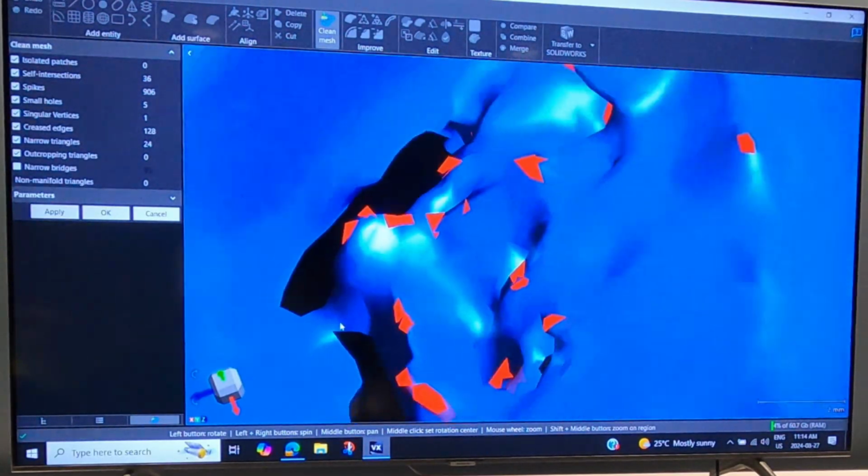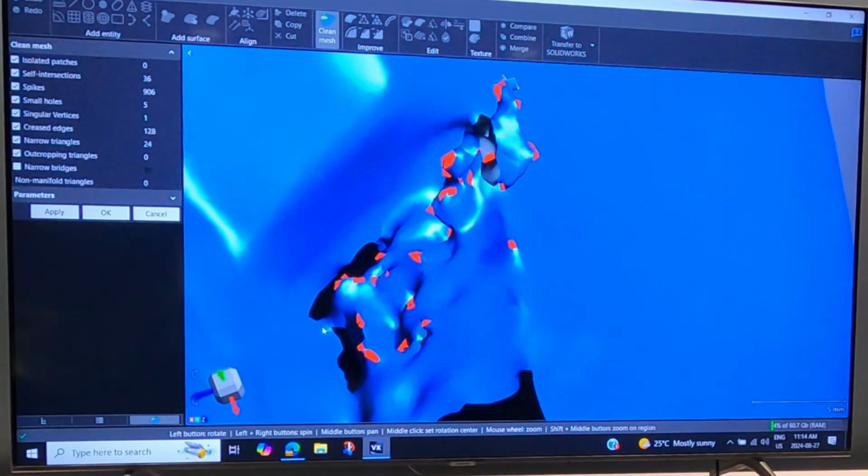But I don't want to get rid of that necessarily. I wouldn't want to ditch this because I could latch onto this to fill a hole after, the way I would want it to be. That's why it's defaulted as not being checked. If you want to get rid of them, you can check it and they'll disappear. But I'd rather keep as much original data as possible if I'm going to bridge and fill holes. At least I'll have the original data to stitch onto. Even if it's not a lot, it's still something. Could be a legitimate connection. Exactly.